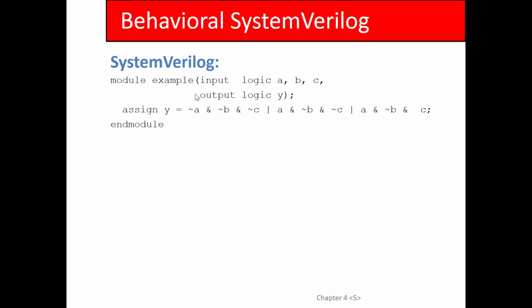Okay, so inside here, the only thing we have is an assign statement. This is called a concurrent assignment statement, and this is a circuit. This statement represents a logic circuit. Everything on the right-hand side of the assignment is the sensitivity list, meaning that when any of these inputs, A, B, or C, referenced on the right-hand side, changes value, it causes Y to be updated immediately afterwards.